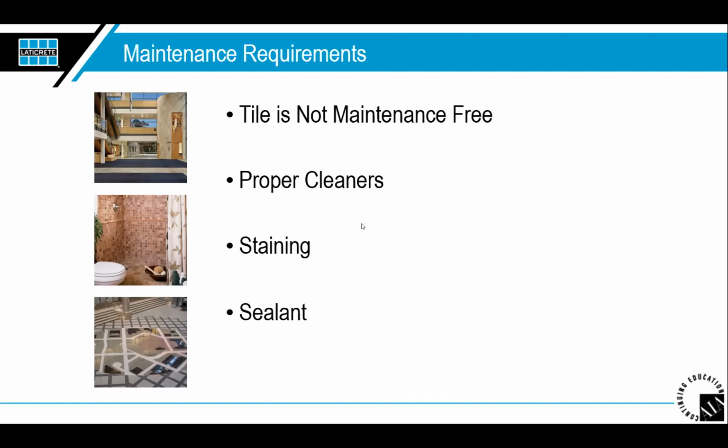So again, with different patterns and things, it wasn't that long ago when we actually had to create a grout joint that was right over top of that control joint or the expansion joint, for example. And now we can actually go around that by filling in the control joints, putting a membrane over top of them that can be sheet or liquid applied, and then honoring it through the installation. So yes, we would honor it through the installation, but the TCNA is going to have specific instructions for where that has to go. Yeah, I'm not in the house anymore, but if I was in control of it, I would have put a membrane down of some kind. Yes, for sure.